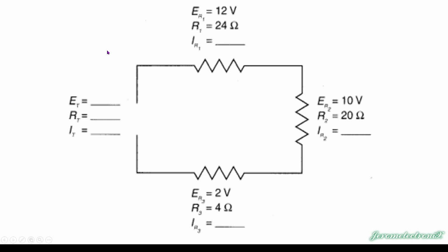Well, first of all, we know that this is a series circuit because there's only one pathway, whichever direction the electrons are going. Every electron must go through every component. Otherwise, there would be branches or choices for the electrons to choose different paths. This is a series circuit. What that means is we're going to use Kirchhoff's series laws to figure this out.